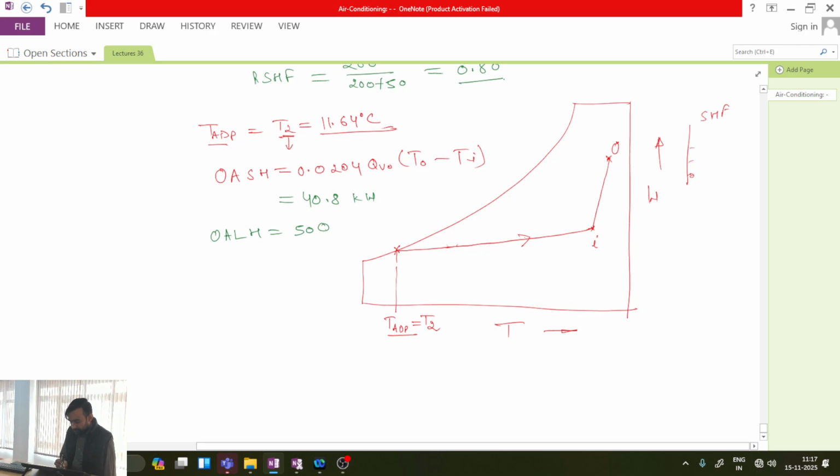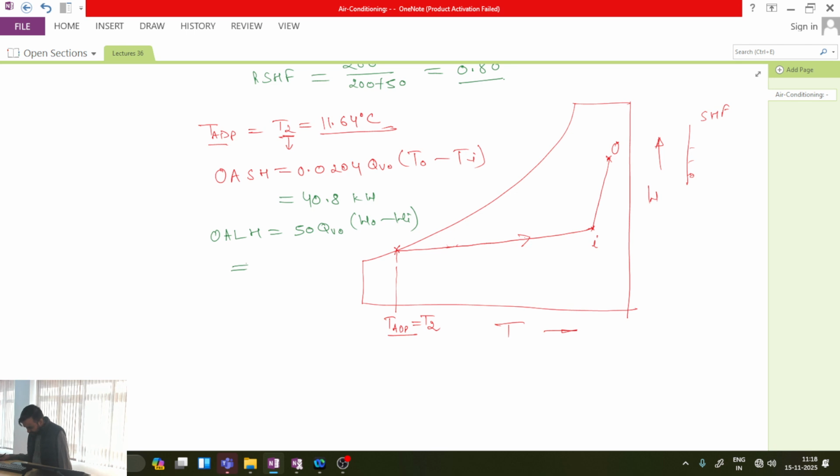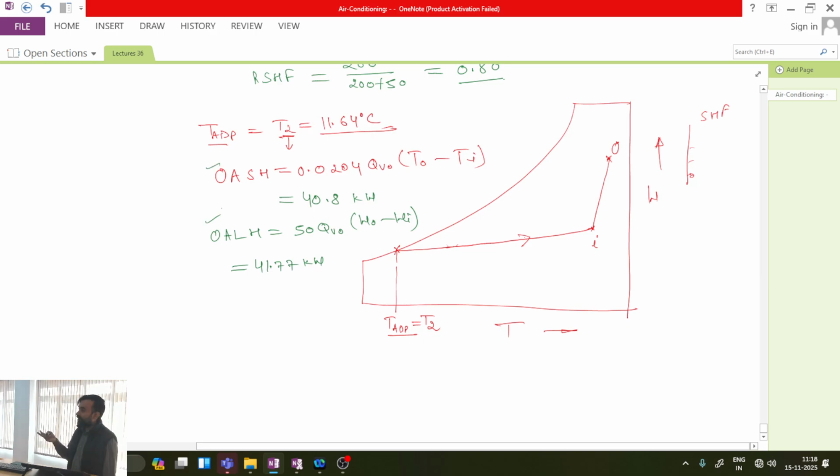Can I calculate OALH? It is 50 into W naught minus Wi. How much is it? W naught and Wi we have already taken from the previous lecture. It is 41.77. Now, if I know these two, already I know RSH and RLH. Can I calculate the grand sensible heat, GSH?